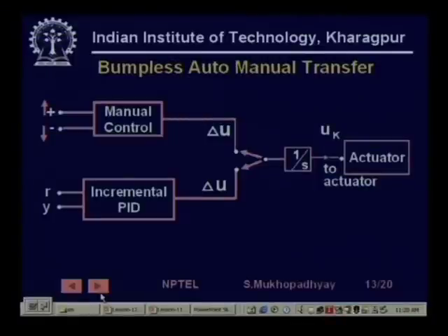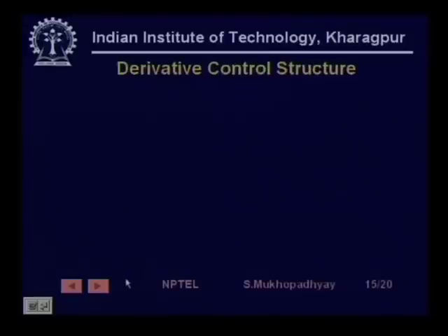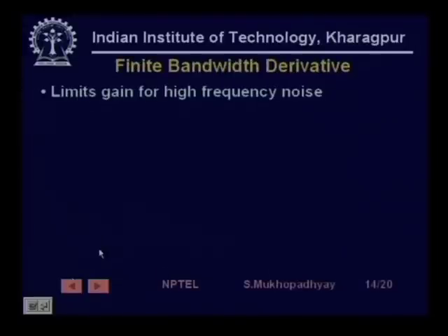Okay. So, these are some problems which you need to take care of when you are trying to implement, especially when you are trying to implement integral terms. Now, let us come to the derivative term. So, let us look at the first problem with derivatives, that is that derivatives typically tend to blow up high frequency noise.